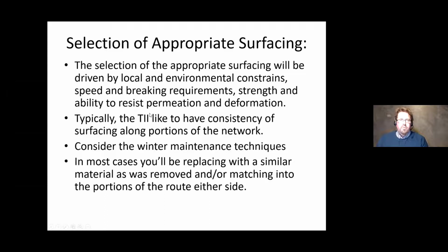So again, the selection of the appropriate surfacing will be driven by local environmental constraints, the speed and braking requirements, the strength and ability to resist permeation and deformation. This is something to consider as well. Is your existing surfacing holding up in your environment? Are you on a roundabout and is your HRA losing all its stone? Likewise, are you in an urban environment or in a rural environment and you're finding you're losing texture because your SMA has washed out? Just be conscious of what's happening. Is what you have there appropriate?